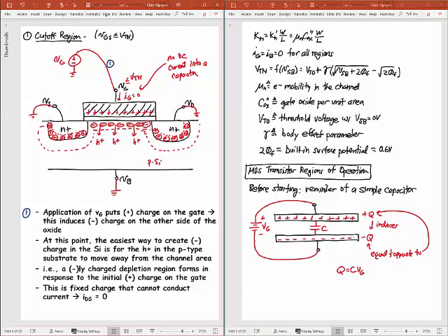Right, so all this now becomes negative static charge. So when I put the circles around this, that means it's static, it can't move. And that's what my MOS transistor looks like after I've just put a little bit of voltage on it. Okay, I haven't put enough to get over the threshold voltage, just a little bit of voltage on it, and so it's off, right?